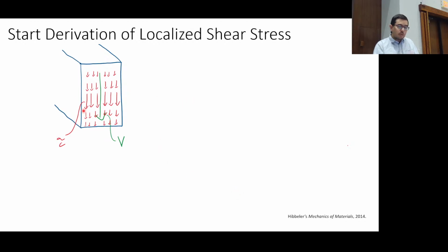Notice again, before we even get to that quantitative calculation, the way I'm drawing these shear stresses, you see that these vectors are smaller at the upper region and at the bottom region than they are in the area close to the neutral axis. And again, these transverse shear stresses are going to be 0 up here or down here on those outer surfaces, which is in contrast to the bending stresses, which are maximum at those upper and bottom areas.